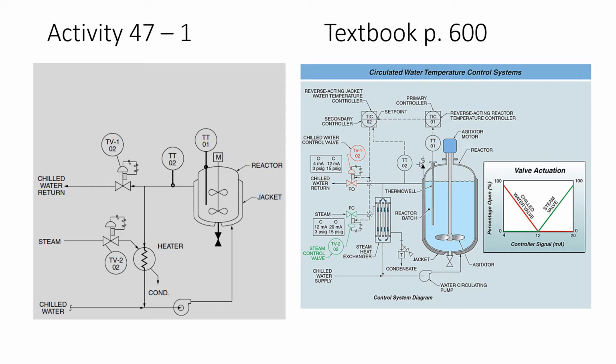Once the temperature gets up to a certain point, the exothermic reaction kicks off, gets started, and that exothermic reaction generates heat, which means that it's going to be providing its own heat in the reactor. Then we can cool it down and just maintain that temperature with this control valve right here. But we want one controller to be able to do it. Okay, and so we are going to add a cascade controller to that.